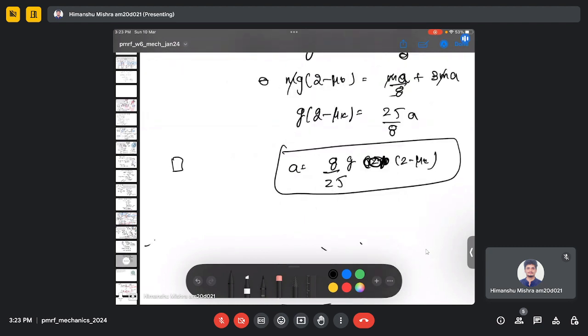But the thing remains the same. Suppose we have three bodies. In all three, you can develop these sets of equations. Now, which set of equations you need to develop is based on your thought. If there is a rotation like a pulley or a disc, then you can use the moment balance. And if there is only a sliding of a body, then you can use the force balance analysis.